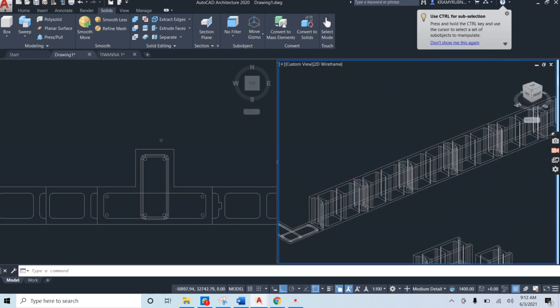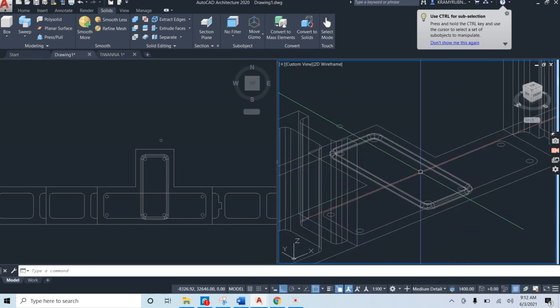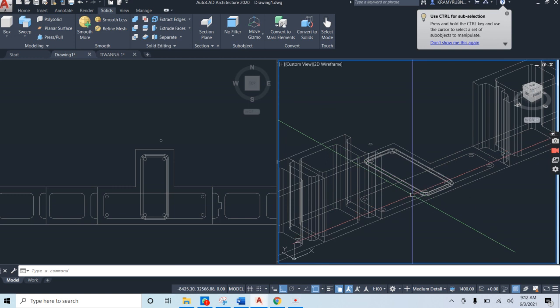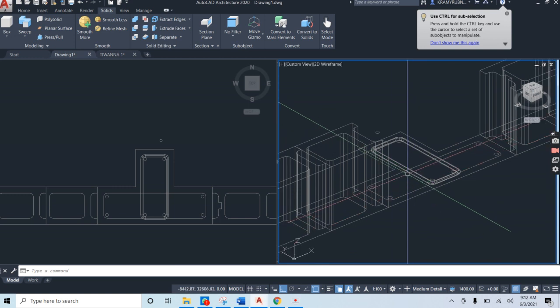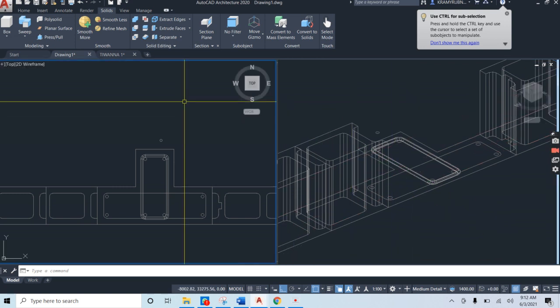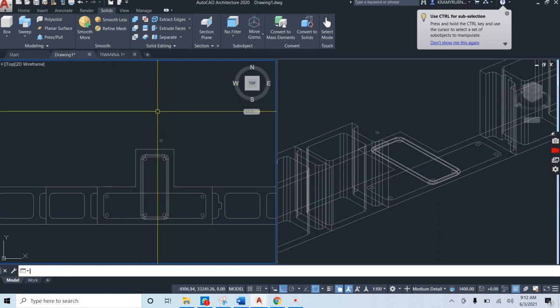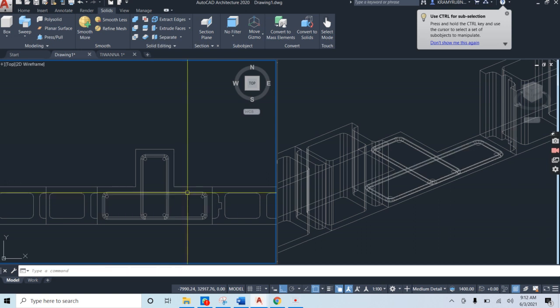And again, if we go and take a look at our I stiffener, I'll show it shortly. Likewise, this circle is to be swept onto this path. Alright, so go sweep, select your circle, enter, and then select the path.